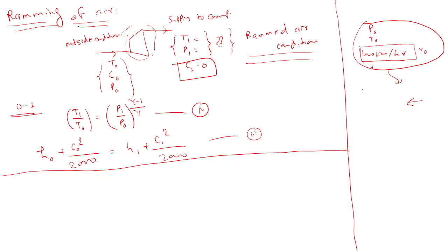So it might break some parts there because there would be very high impact loading. Then sometimes the air velocity would be here, and again the direction will change. It will come here. So what will happen? Sometimes load would be here, and then cyclic loading will come, and fatigue might also come. So many problems will come with the high velocity of air.